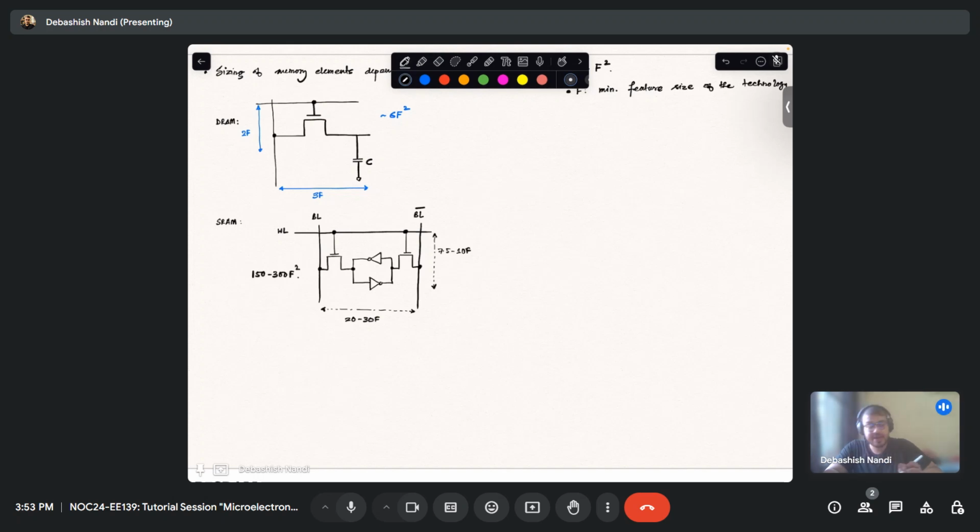So you can see, right, that your capacity of SRAM has to be lower to accommodate higher speed in the same area, right? Because it needs a larger W by L of the transistors, or fatter transistors, okay? So that is DRAM, that is SRAM, and for your 2D NAND flash.